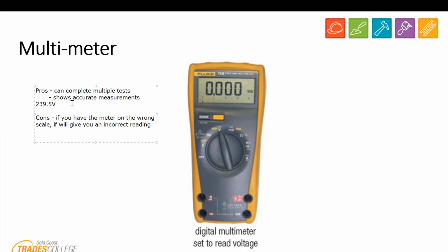Other cons as well: the biggest one I find that students have an issue with when they're testing in class is that the ports at the bottom of the tester need to be correct for the tester to measure the desired value. Like I said, guys, if you want to use this as an ammeter,